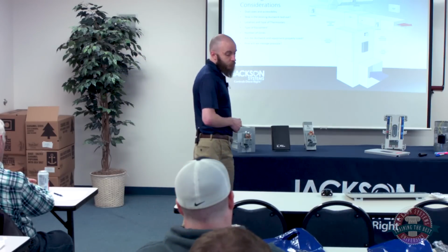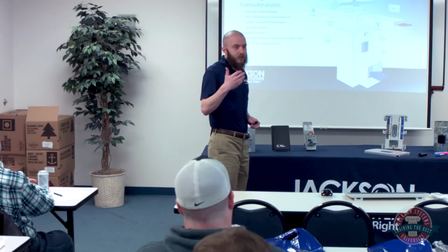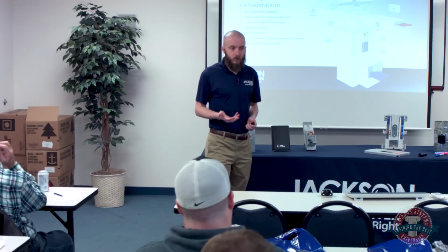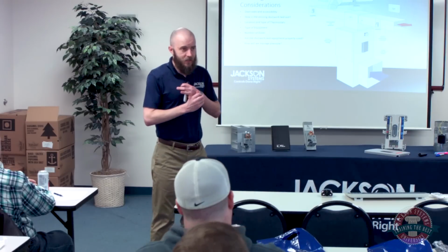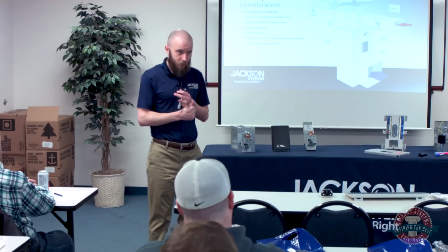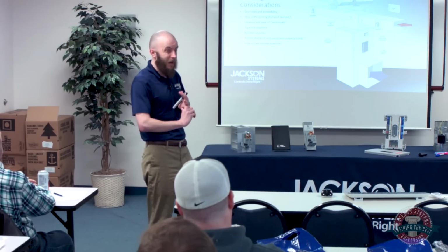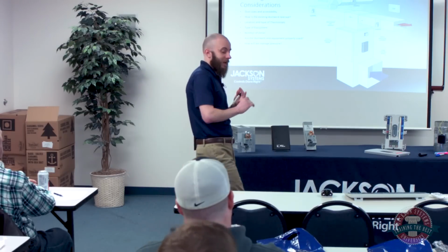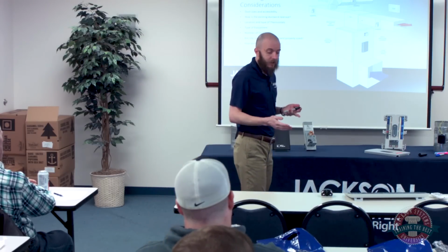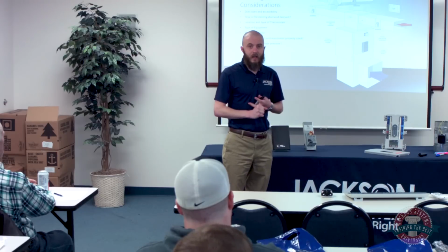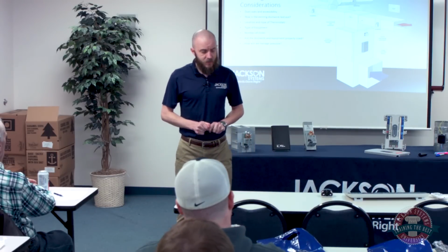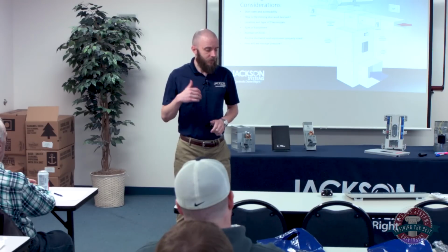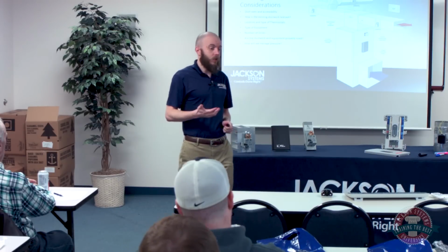But at the same time, you do need to know how the system's going to react to the pressure increase, whether that's by adjusting the settings, adjusting the setup on a variable speed blower, installing a bypass damper, or installing a zone system with some kind of static pressure relief, like the IO ESP system. You have to deal with that pressure, or at least know what it's going to do.